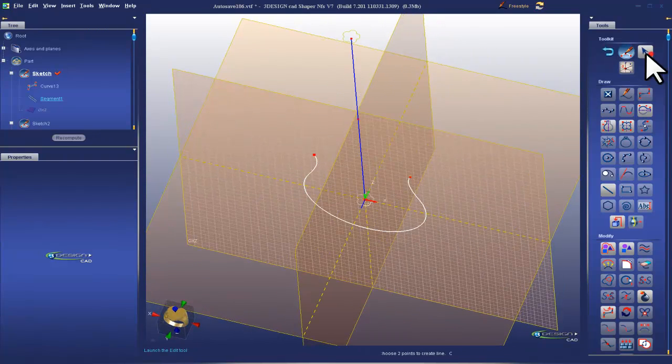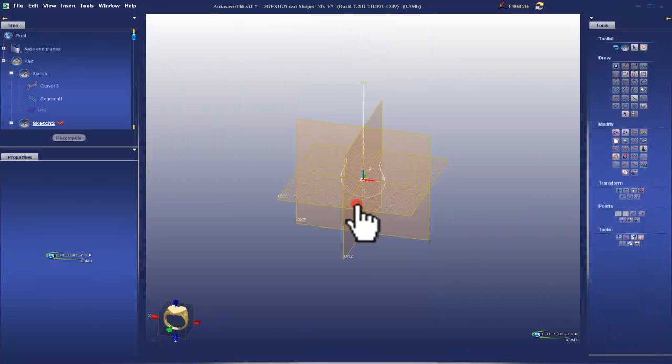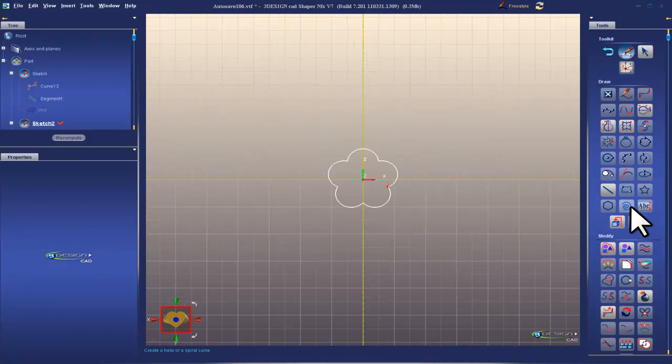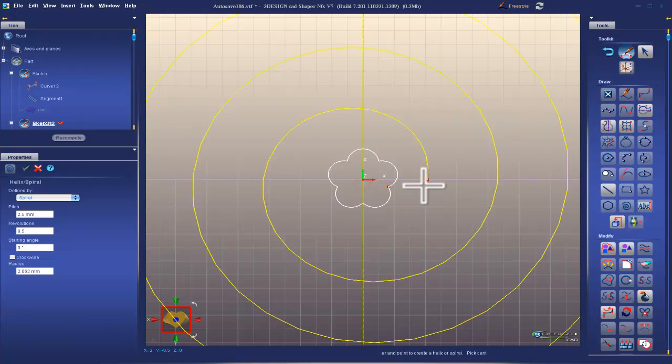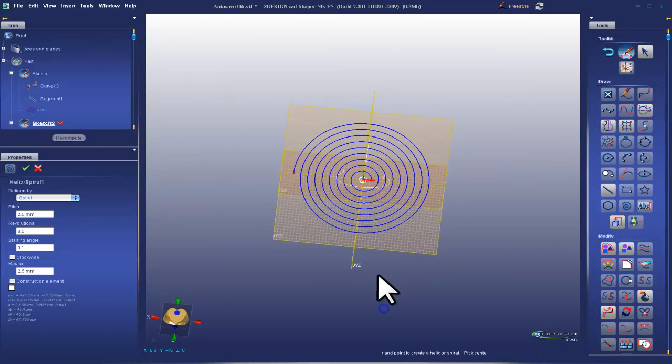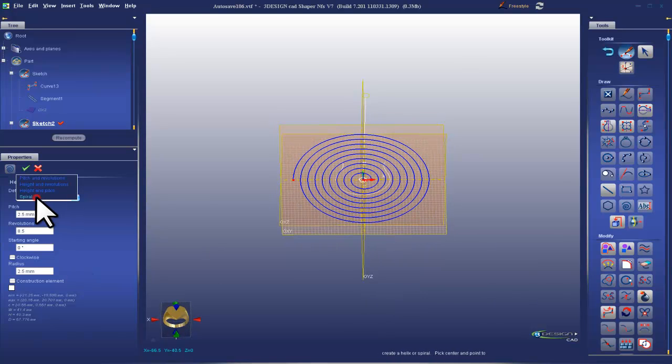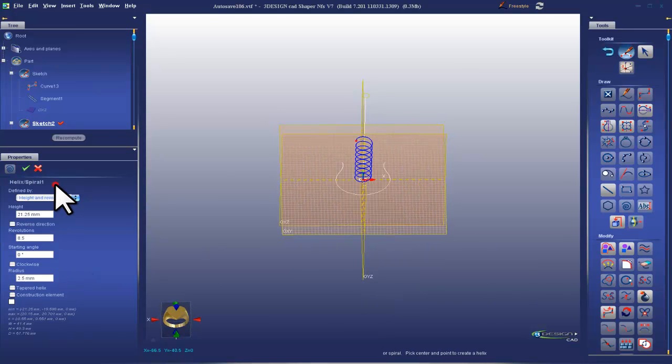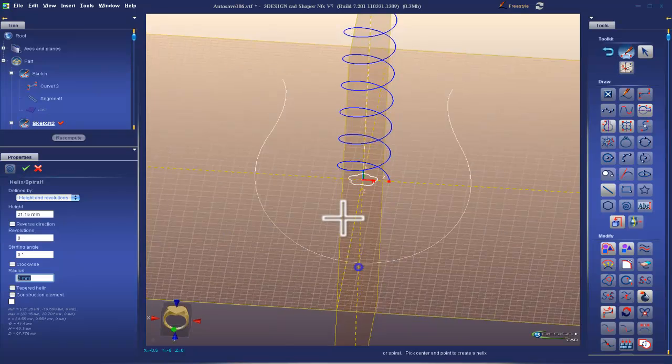And then lastly, I'm going to go back to the top view sketch, and I'm going to draw a helix. It's okay, I can just click on a spiral and then go back in and change it to helix height and revolution. Height will make it 45.7. Revolutions will make it 8. And radius will make it, I don't know, 2 is fine probably.